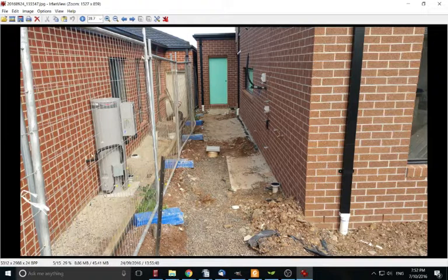Even a good concreter should be able to just remove that and not touch anything, concrete that, and then the plumber comes along and reinstalls that, and it should be a pretty straightforward job, because sometimes I've reinstalled them and managed to still get it connecting up to the original heights, depending on how the pipes change. But yeah, they can do it pretty quickly. It's usually no more than an hour for a plumber to reinstall that, as long as it's all reasonably close and nothing major. And I think it's really something worth doing.